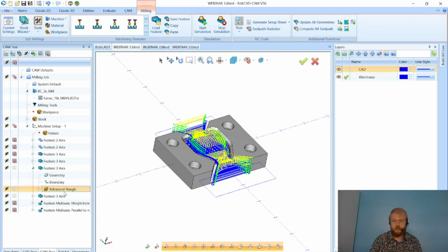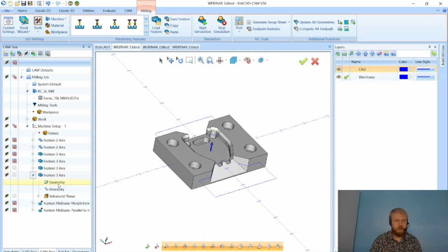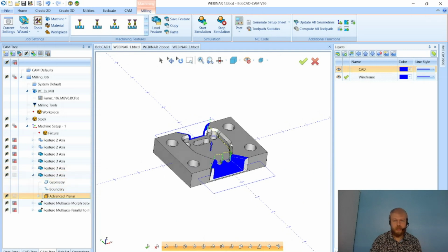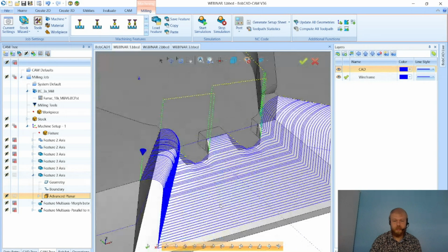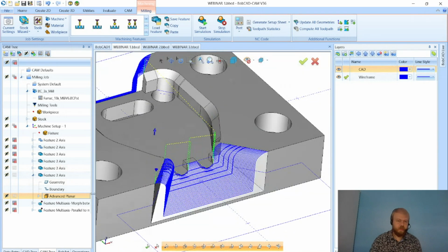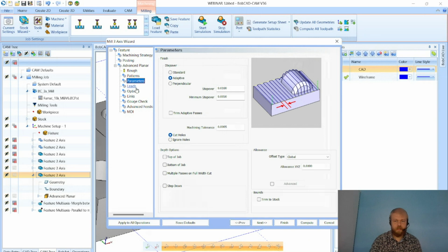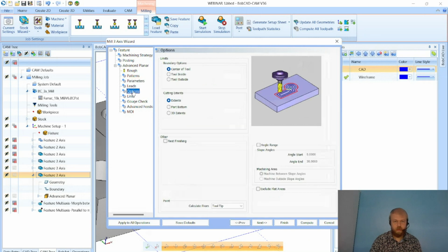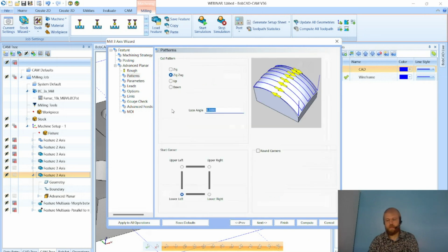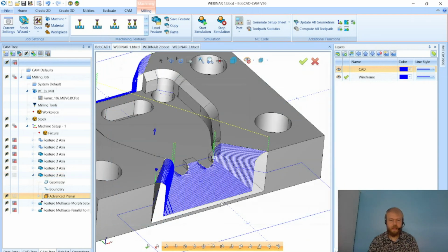We went through the roughing with this part file. We went through the planar toolpath for top and bottom. Now the planar toolpath, again, isn't very efficient. We'll even take a look at the simulation first. Once I set this to 0 again, or 90 again, for the angle direction, just going up and down here.